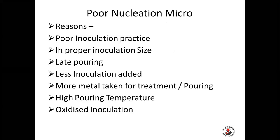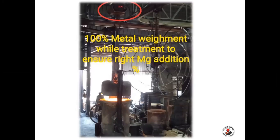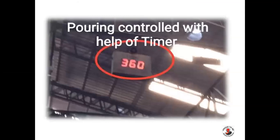The reasons: poor inoculation practice, poor inoculation size, late pouring, less inoculation added, more metal for treatment or pouring, high pouring temperature, oxidized inoculation. You can see here some good practices to be followed for better nucleation and to get good consistent quality of metal, that is 100% weighment of metal, to ensure your inoculation percentage is correct. Pouring control with the help of a timer will help you in controlling your inoculation fading time.